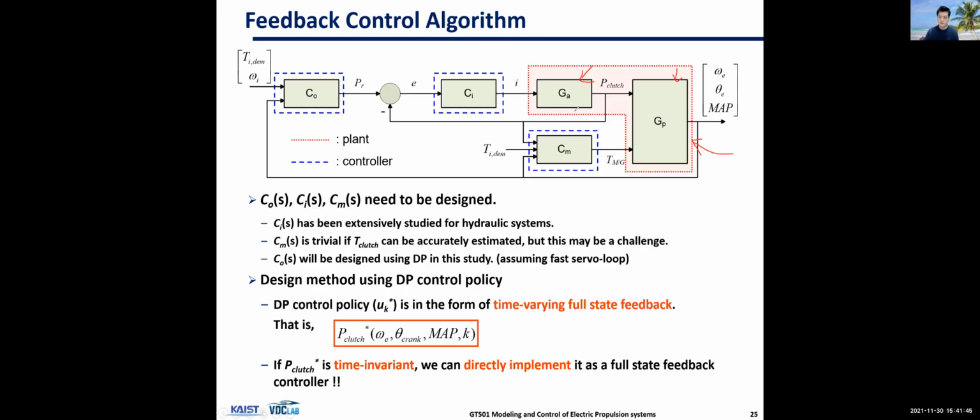But for a real-time control problem, we need to consider actuator dynamics. So we need to design the clutch pressure controller, a motor controller, and a controller that outputs the reference pressure.